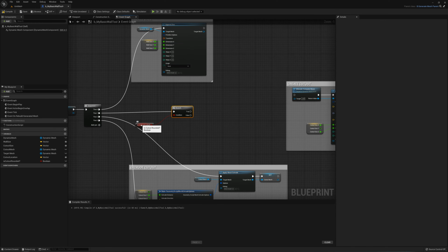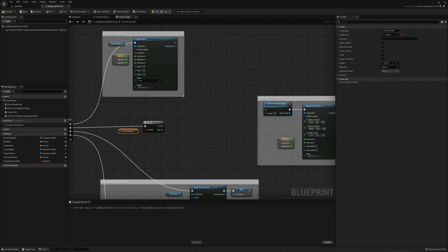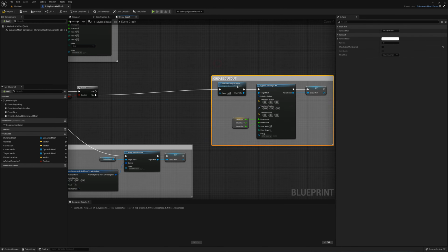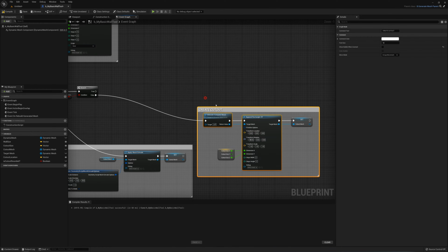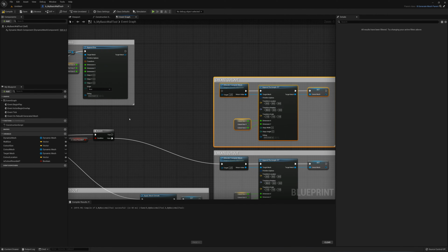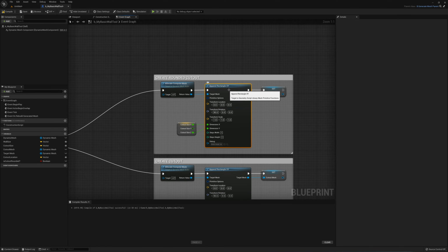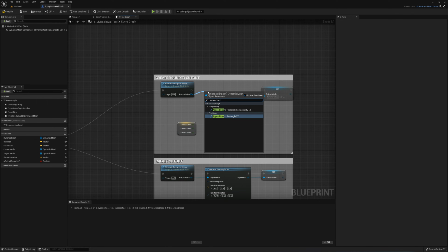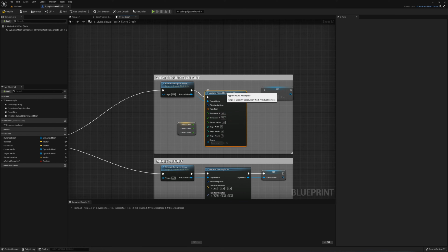Okay, and so if it's not a rounded cutout, then basically we want to do what we're doing already. So we'll set up our false to that one. And I'll just grab all of these nodes here, duplicate up here, and we'll plug in our true node over here. And I'll just adjust the comment here. We'll create a rounded cutout. And what I'll do is delete this node, the append rectangle node, and we'll make a new one here called append rounded rectangle XY.